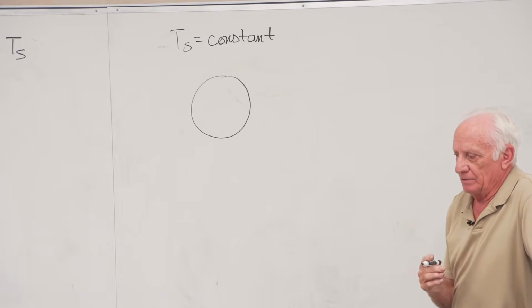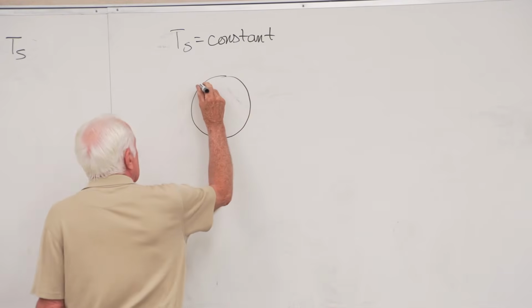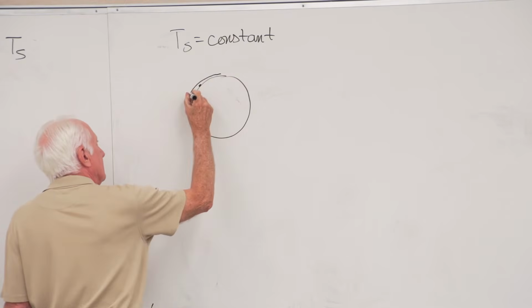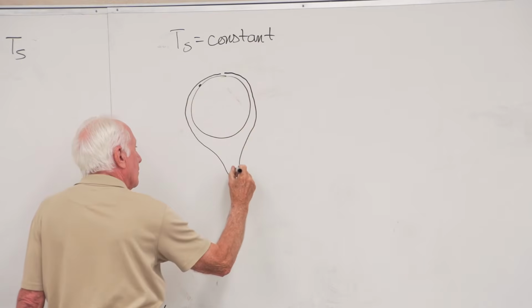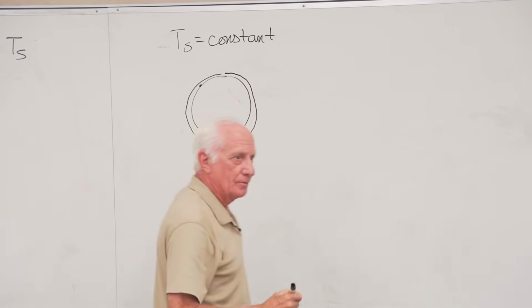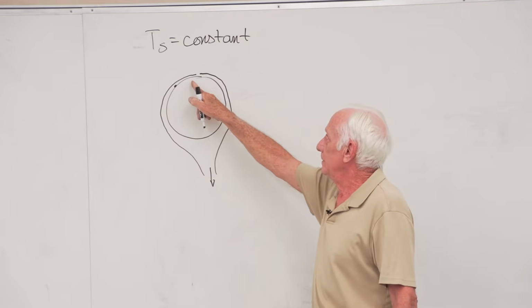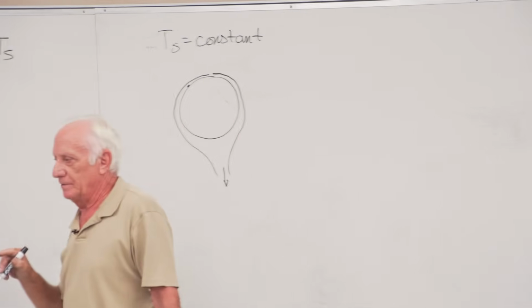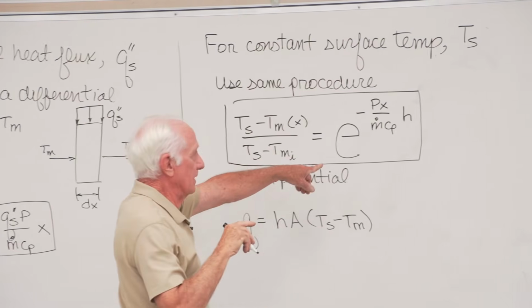So the water droplets condense at the saturation temperature. They turn from steam to liquid water. They then run down the tube in the hot well here, where they're collected and pumped around. And of course, guess what this is? The temperature everywhere along here is the saturation temperature of the pressure in the condenser. Okay, that's what I'll use.